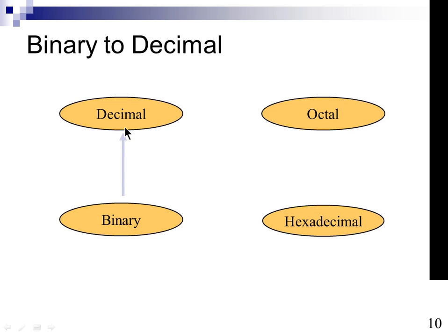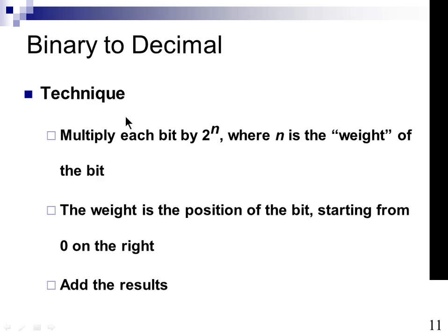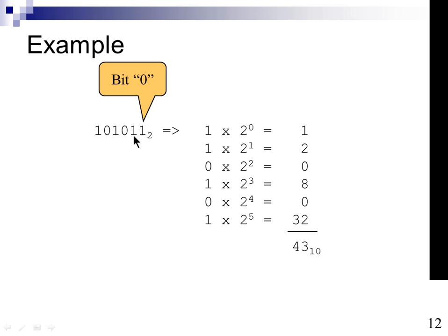So if I want to convert a binary number to a decimal number, this is a longer binary number, so it's not that easy to convert by manual calculation. We have to follow a process for that. How do we do that? From the LSB side, this is the weightage that we add, and we multiply it by that weightage, and finally we add up all of that, which will give me the decimal number 43 in this case.